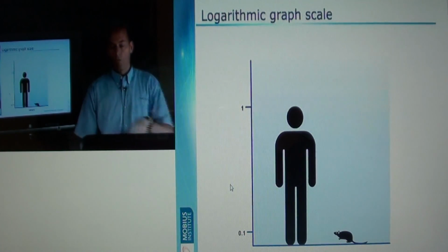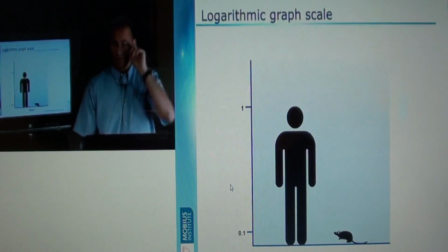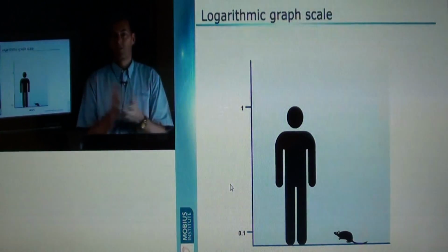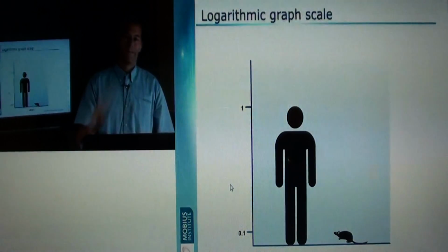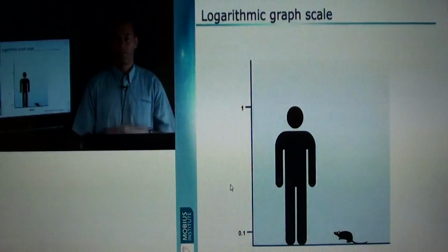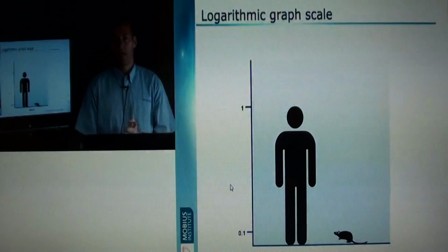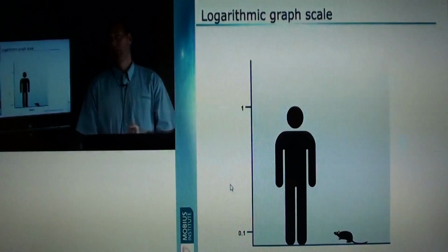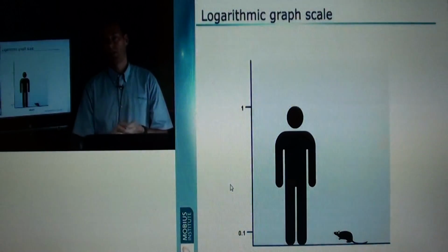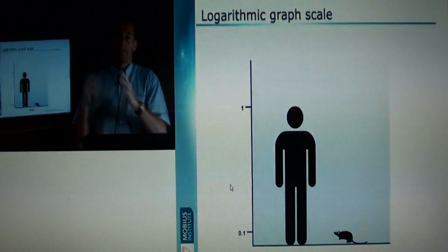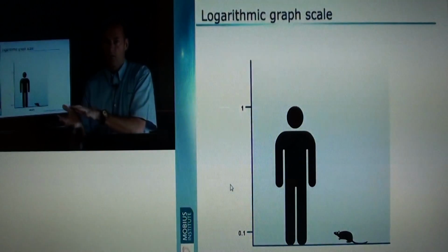Now, if I want to know that that mouse exists, you see, I reckon vibration analysts fall in two camps. Some guys will say, man, if it's a mouse, I don't care. If the vibration amplitude's that low, I don't care. But are you the same person that's using enveloping or peak view or anything like that? Well, if you are, sometimes that information's right there in your spectrum.